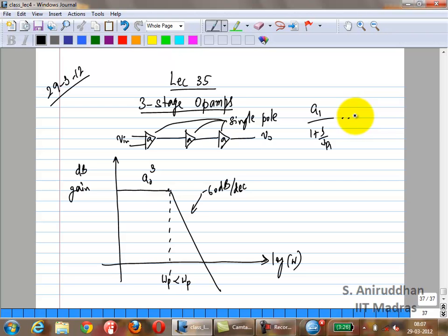Okay, so that is one thing you can do. What about the gains? Can you make the DC gain the same? First of all, is that optimal? What do you know about the gain and bandwidth trade-off? We know that low gain stages have fairly wide bandwidths and vice versa. If you try to make very large DC gains, usually the bandwidth is very small, right?